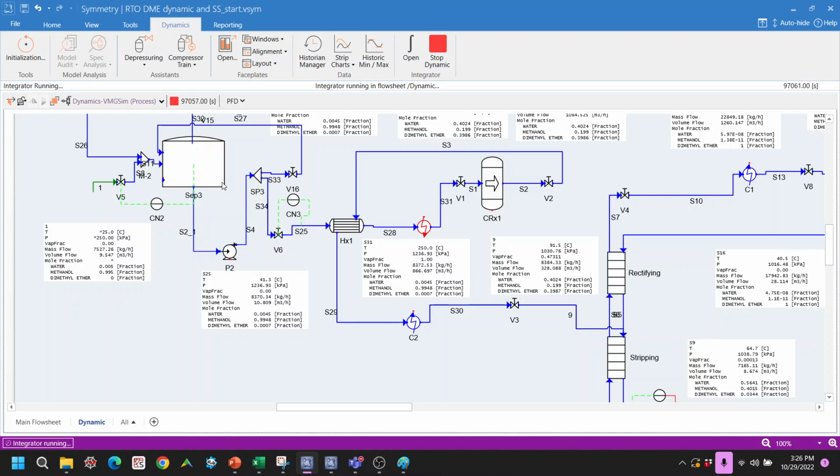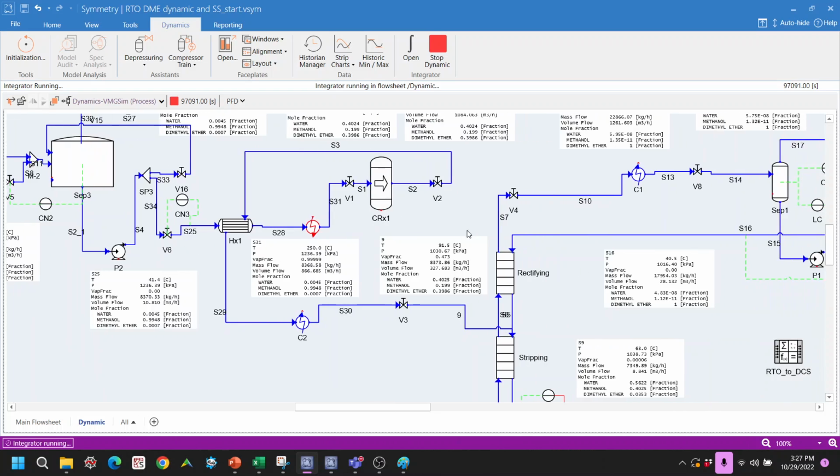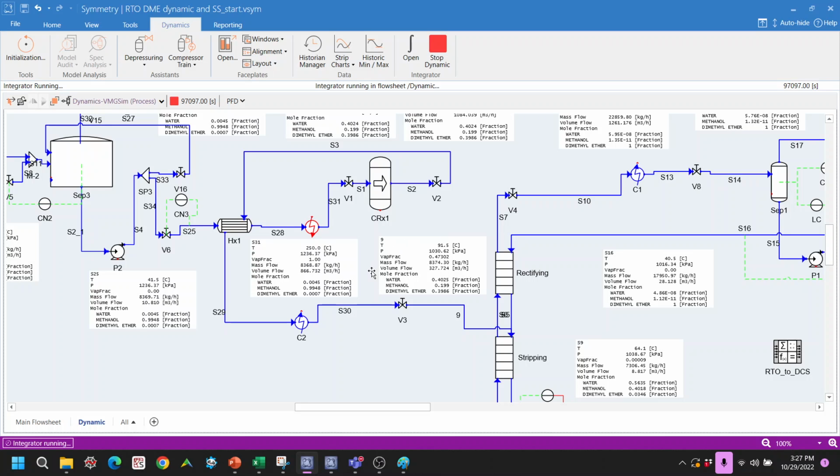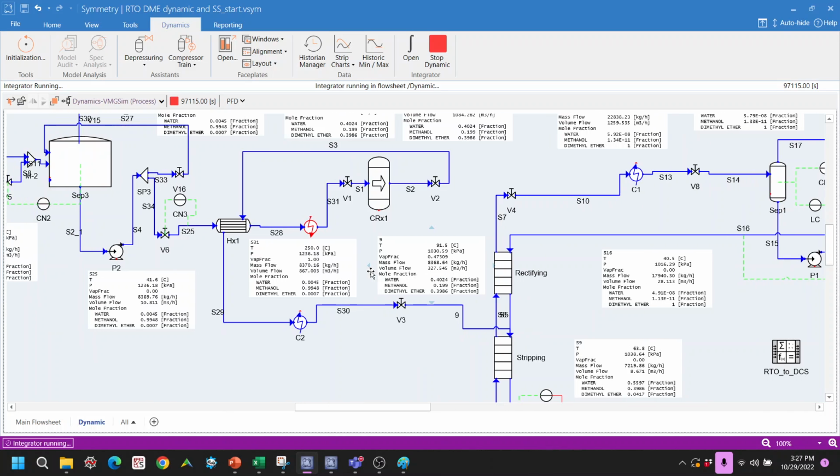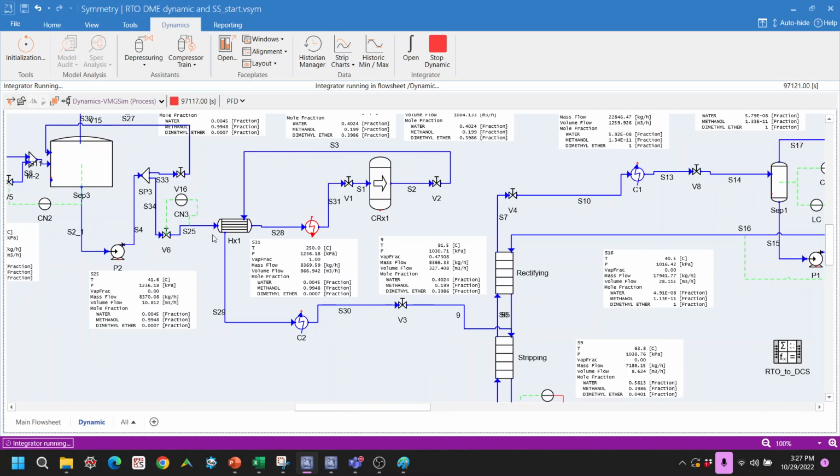So you have a tank, right? It fills with liquid, and then you pump it and recycle it until you have sufficient pressure, and then you open this valve and let it run through the exchangers, and then this guy will make sure. It was exactly like an actual plant. Can you mean that at time zero recycle flow is zero? At time zero recycle flow is zero. Yeah, you could do so. If you close this valve, then it becomes zero.